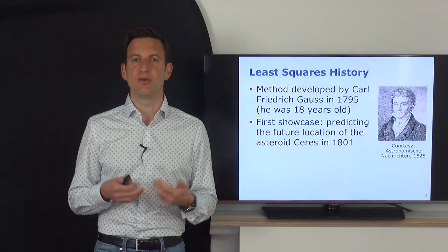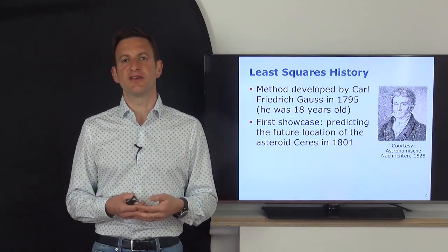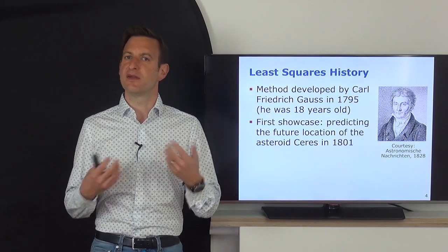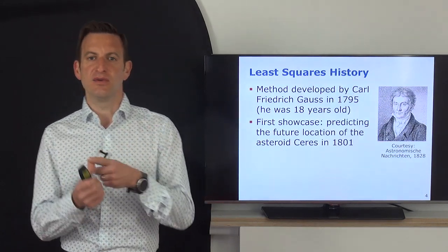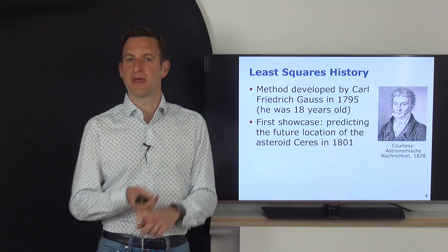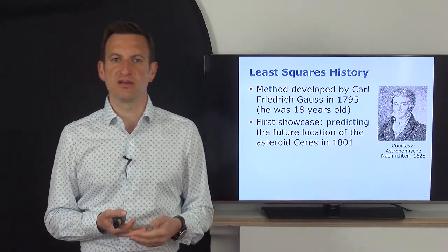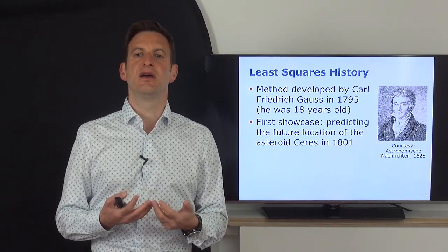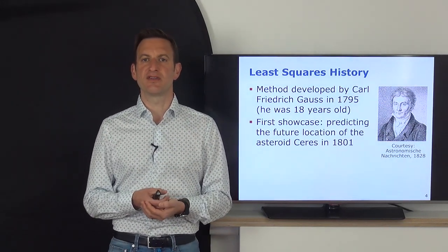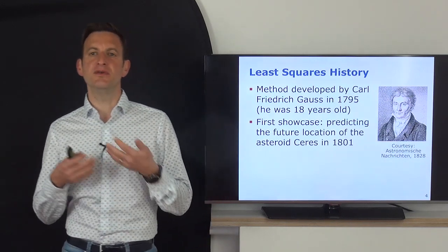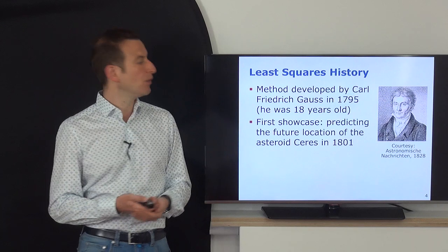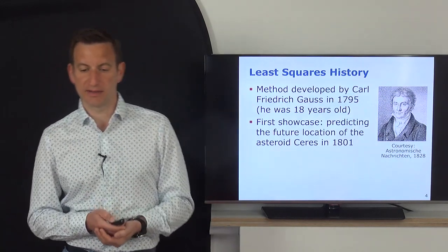The only thing which is new in robotics is what kind of constraints, what kind of observations we have, that we are interested in certain things like doing this very fast, treating this as an online problem, not as an offline problem, having other data association challenges in there. So there are a lot of things which are special in the way we address the SLAM problem, but the overall idea of using the least squares approach for solving this mapping problem has been around for quite a while.